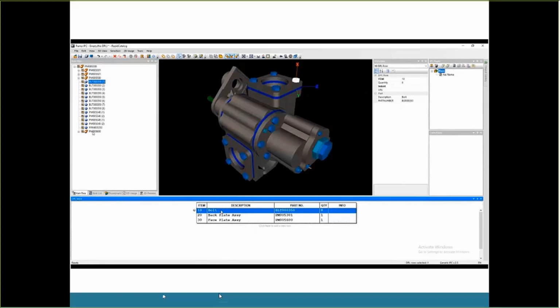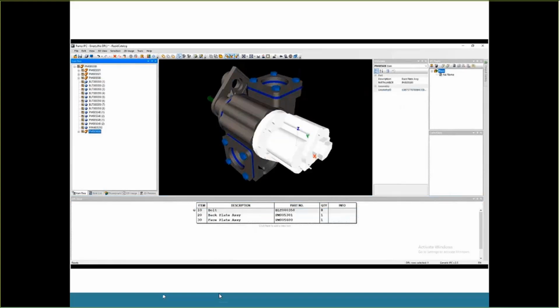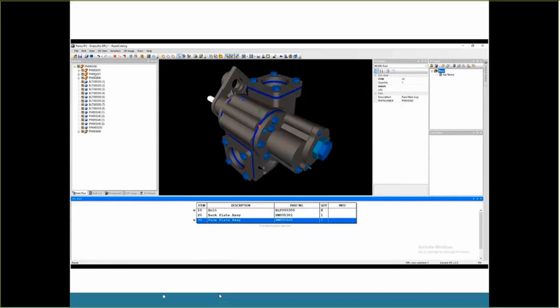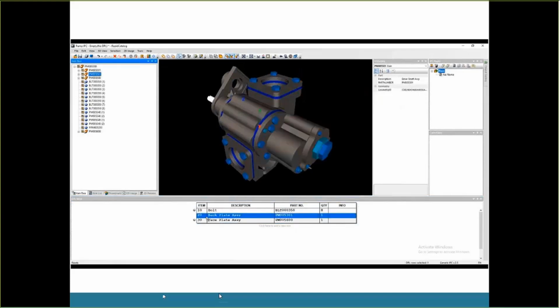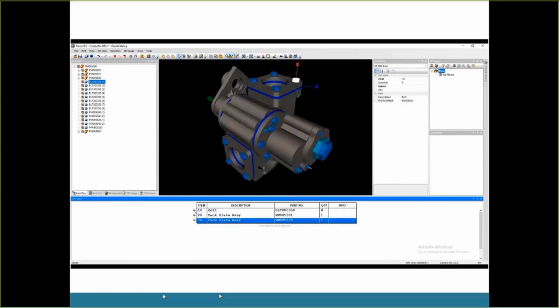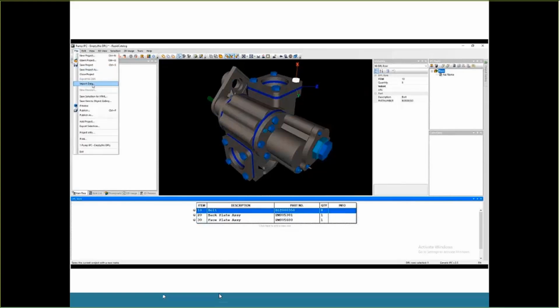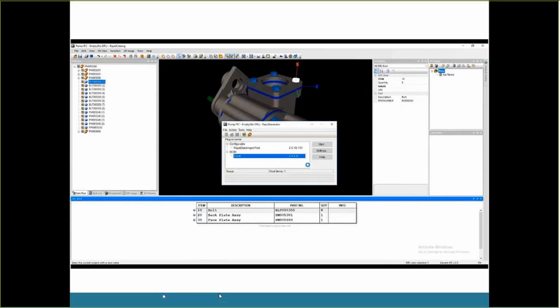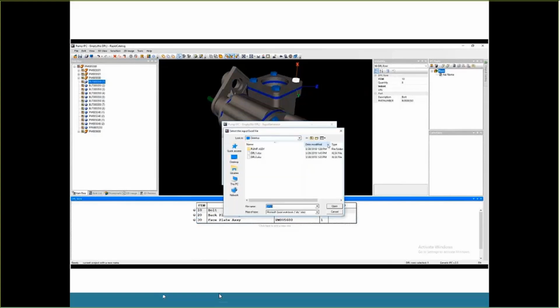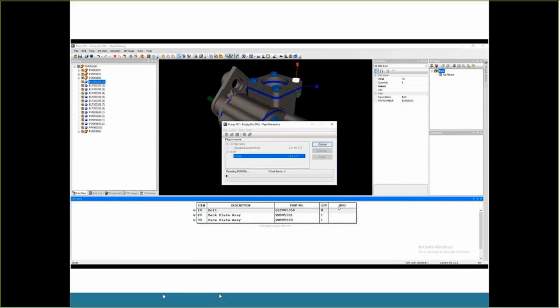We can directly make the links to the 3D geometry by dragging and dropping the parts to proper placements in the DPL table. And now we will import the additional DPL table information from Excel spreadsheet number 2, which has the same part number of the bolt, but a different description for that part number.